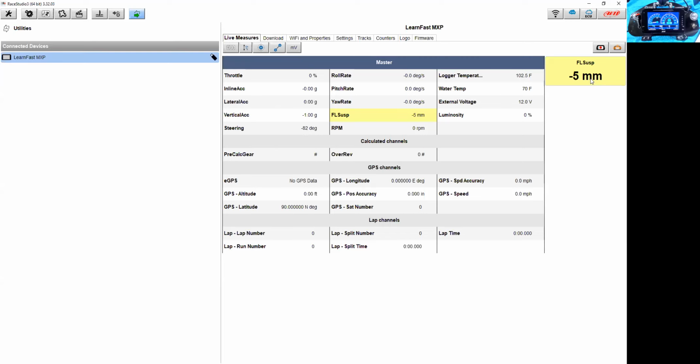I'm not sure where the story's going, actually. Oh, when you and Andrew had the Miata and you wanted to know the bump stops. Yeah, we had a spec Miata and we had suspension sensors on it, and some people were thinking maybe we were cheating and playing with shock sensor data because shocks are spec, so you can't do anything. But what we were actually looking for was a ride height sensor, and we were looking for when that car was hitting the bump stops, especially on the right front corner at Topeka, Kansas, on that particular track.